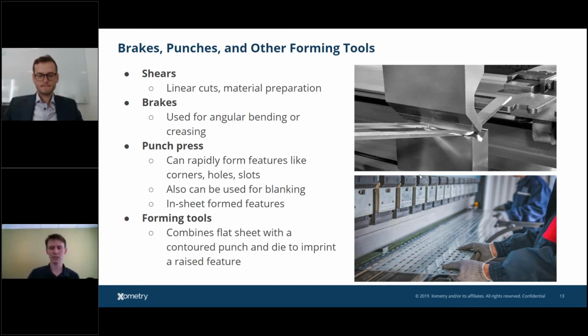All right. And so this is a slide that we're talking about. So we have our forming tools, right? We're making our parts here using different types of things, usually a brake, some punch press, different types of forming tools. But how do you feel when you just get a flat pattern? So when I just get the flat pattern, I always have to ask for the 3D model. I always have to ask for a complete drawing because we're responsible for the part to work, right, and to be dimensionally accurate.